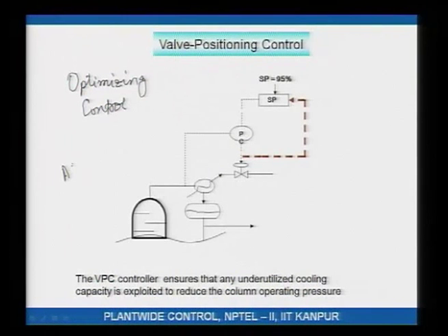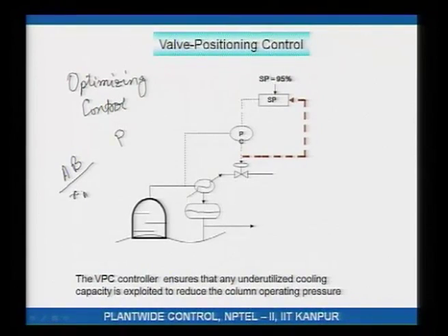Now, since the pressure is floating, note that if you take a binary mixture, an AB binary mixture, let us say, for a given pressure P, if you specify the composition of one of the components, the other mole fraction would be 1 minus that. So, if you specify, let us say, X A, and if you do a bubble point calculation, the temperature at which, let us say, a 30% A mixture boils at a pressure of 1 atmosphere is uniquely determined, it is a unique number.